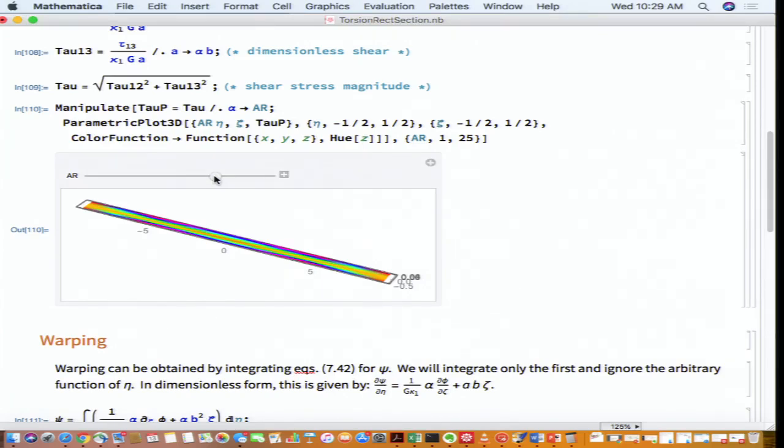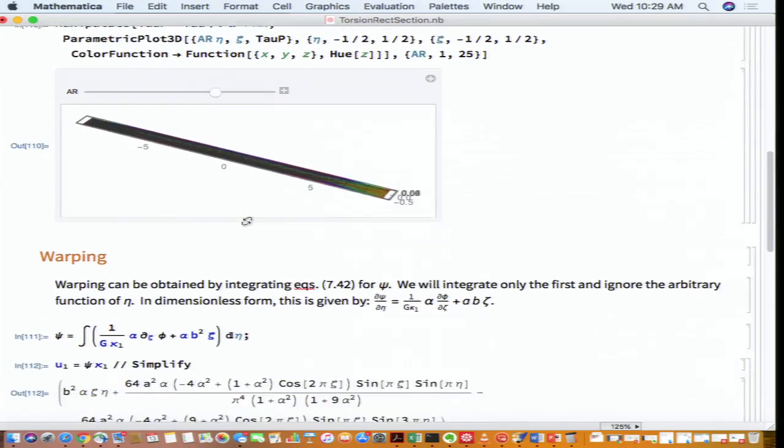So even if you use a very good solution to solve a thick problem and you enforce the dimensions of a thin cross section, you obtain that the shear stress variation is very negligible when you move along the width of the beam. And we will just make this assumption now, and capitalize on it to make our equations simpler. That's what we are going to do in the present analysis.